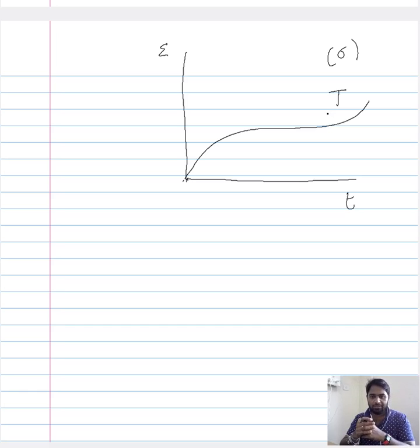And we saw that the initial stage, this stage, is referred to as the instantaneous creep, as it just follows once we apply the load. One primary difference between tensile testing and creep testing is that in tensile testing the loading progressively increases. However, in creep we immediately impose a load, and that immediate loading condition results in the instantaneous creep.